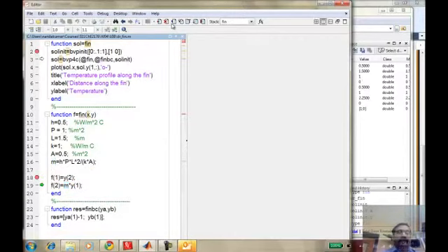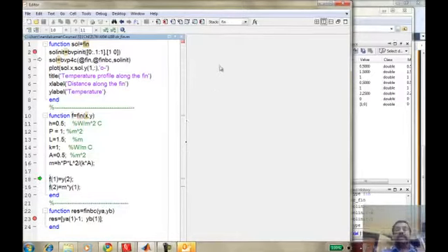So if I execute these, now it is ready to go out. Where does it go out? Back to BVP4C. That's where they came from, right? So we'll go back to that. But it will carry with it these two values for functions, F1 and F2, 0 and 2.25. It will carry this back, okay? And then the interaction between BVP4C and fin takes place many times, okay? So it comes back. Let's set up a breakpoint in the boundary condition and remove this and see when does it come to the boundary condition.